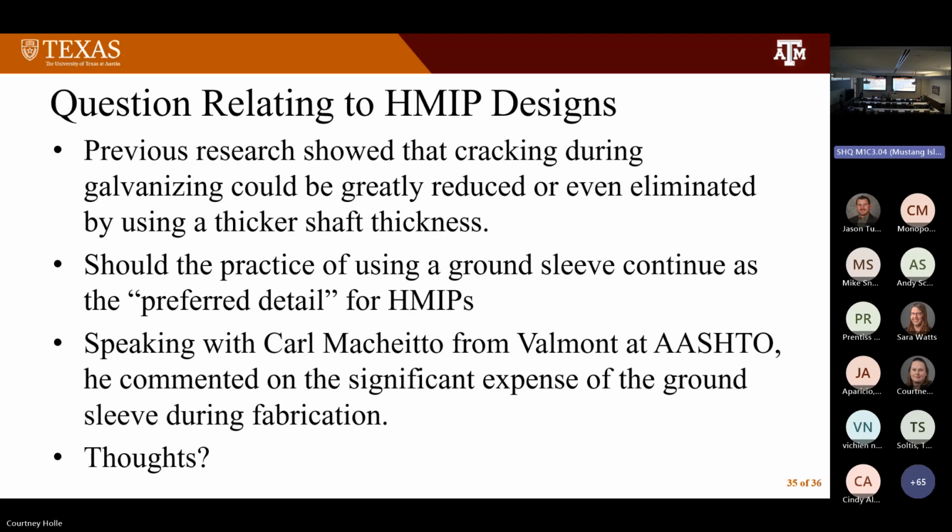You do find that when you look at crack growth versus time, you want to get to it in the stages as the slope of that curve is increasing. You want to make sure you don't get to that stage where it's growing quickly.